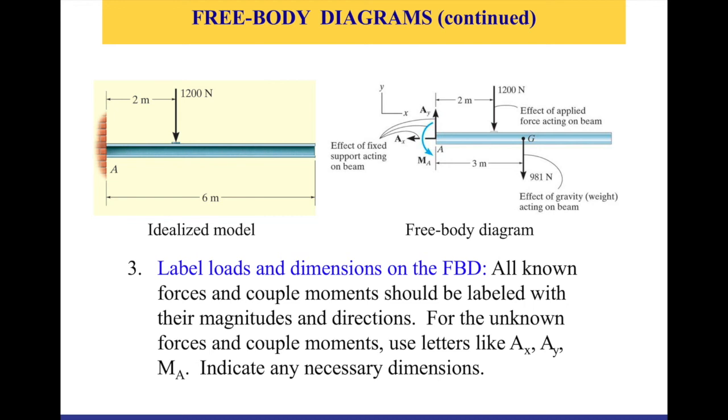Usually, in order to solve for unknowns using the equations of equilibrium, we select the point around which we want to measure the moment to be the point with the largest number of unknowns, especially the reactive forces. We're going to solve a problem about this and show you how to do it through an example. I hope that clarifies why we are interested in equilibrium of rigid bodies.